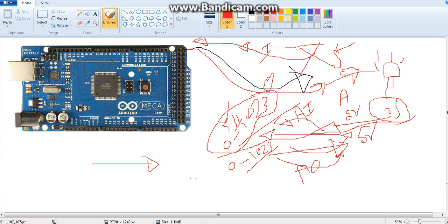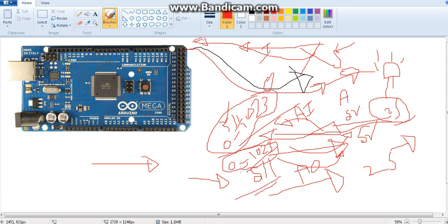So now when you are giving an output, there's a keyword, I will tell how to give an output. If I am giving the 511 value as an output with the output command, then we should get 2.5 voltage output in the particular pin, right? If I measure it, you understand what I'm telling? The same thing is happening the two ways. Okay, 0 to 1023. You understand this, guys? I hope this is understandable, right? So the thing is happening the other way around.